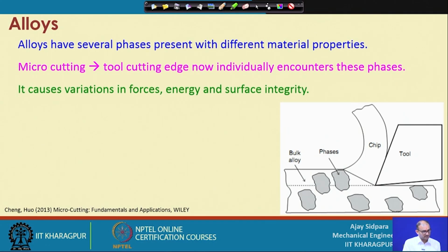Now, coming to the energy. When you are cutting through the soft material, you do not need very high power at the spindle, but suddenly it encounters this grain, then you have to supply more current to the spindle so that it can overcome the resistance of this hard material, and that is the reason your energy variation will also be large. Again, soft material you do not need so much energy, again hard material.